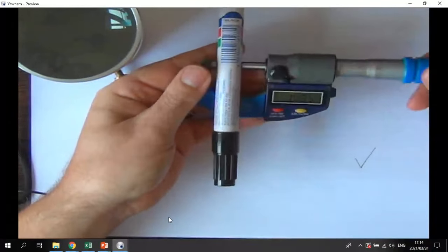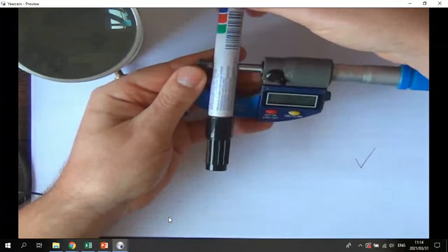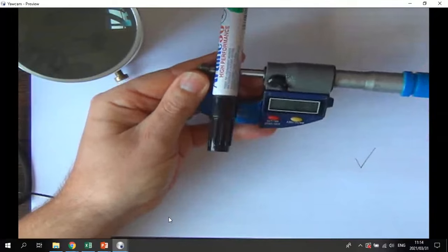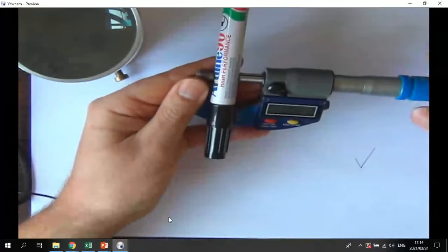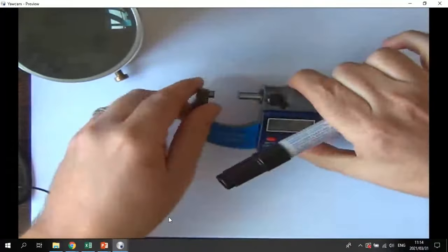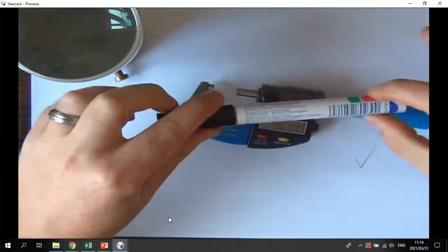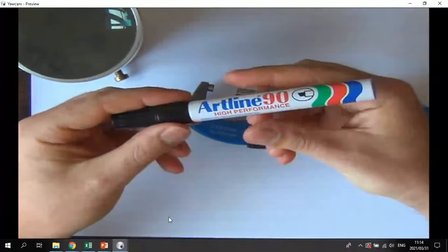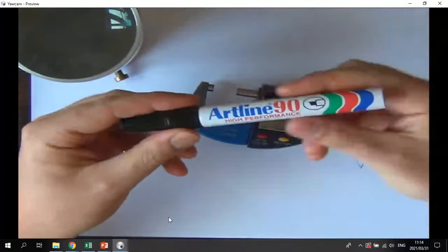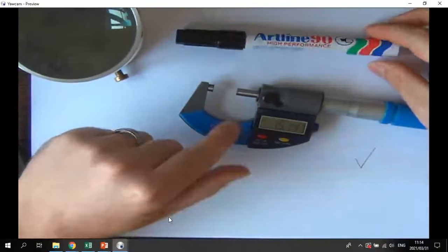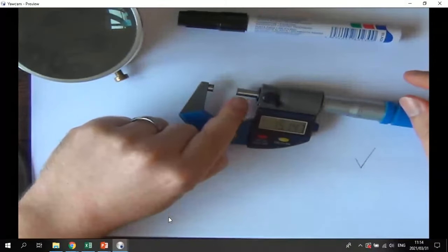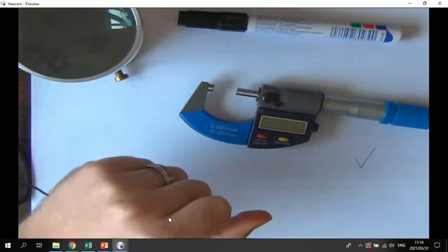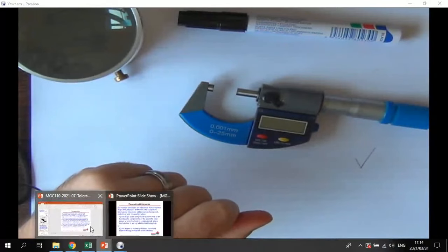There we have a 14.85. And there we have a 14.87. So one could specify exactly how cylindrical this pen needs to be. Obviously, this is a pen, so my hand won't notice a 0.1 millimeter variation in the length of this pen. But if this was a precision instrument, for example, that little shaft in there, then I could specify, or have to specify, a very, very tight value, otherwise that shaft won't function correctly.